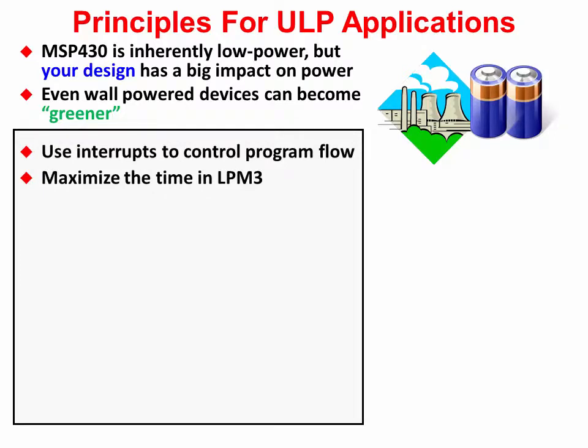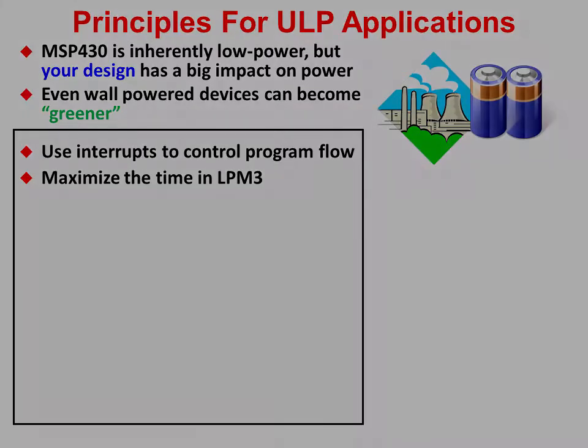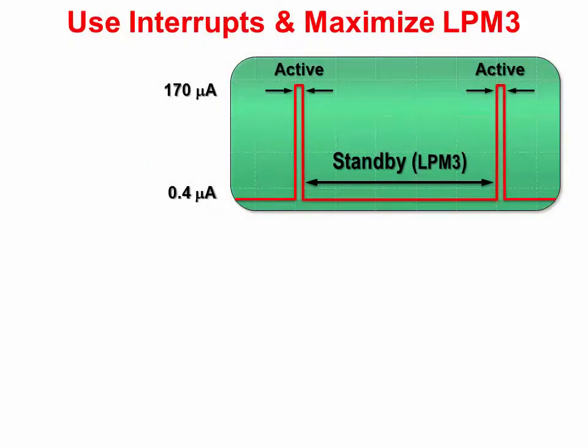As we've just seen in the first part of this chapter, low power modes and interrupts go together. Used appropriately, low power modes can help extend the battery life in your system. Visually, how might this look? Since most embedded system designers already use interrupts to control the flow of their application, half the battle is already done. With this in mind, we can put the processor into standby while waiting for an interrupt event.